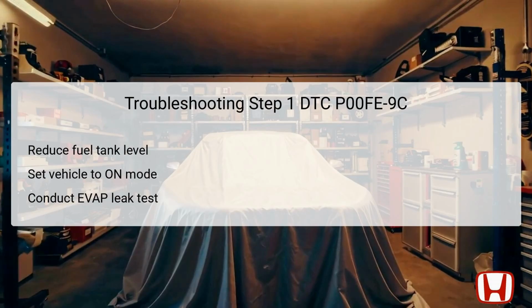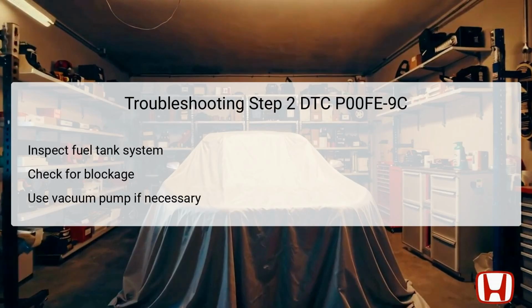After that, you will select the EVAP leak check module test using the HDS, or Honda Diagnostic System. The HDS will assess if the test result returns normal or indicates a failure. If the test does not return an OK result, it signifies that the failure is duplicated and further investigation is warranted. A valid test is key in confirming whether another inspection is needed for the primary components of the EVAP system.